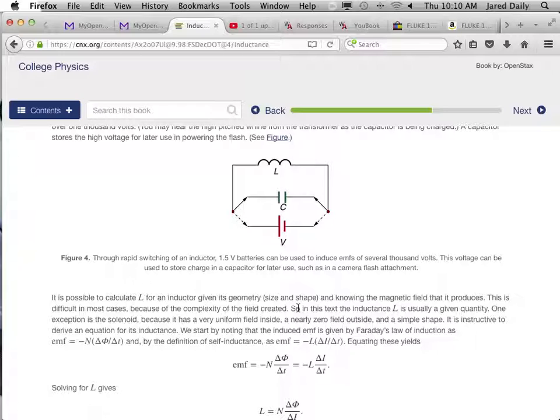What that does is it slowly ramps up the energy between the capacitor and the inductor. The inductor stores the energy after time. The capacitor stores the energy immediately. So when you switch to it, the capacitor gets all that energy, and then when you switch off of it, that capacitor puts that energy into the inductor. Then when you switch back to it, you store more in the capacitor again, and then it puts it back in the inductor.